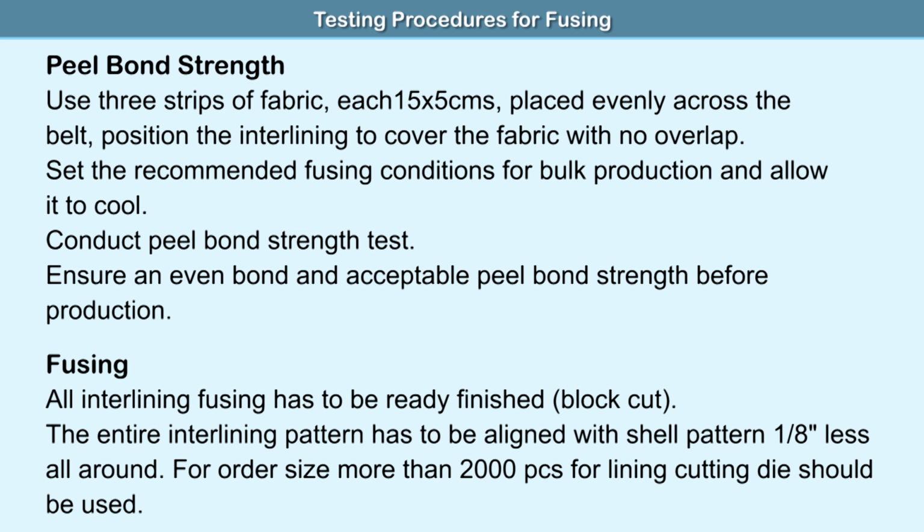Set the recommended fusing conditions for bulk production and allow it to cool. Conduct peel bond strength test. Ensure an even bond and acceptable peel bond strength before production.